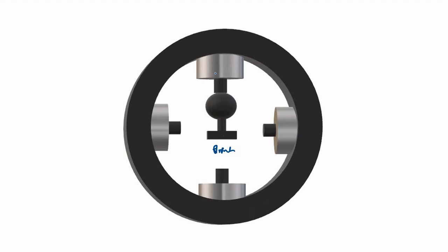Whenever the object rotates, it strikes the wipers placed at different positions, let's say the angular positions 0, 90 degree, 180 degree, 270 degree, and then 360 degree here, like this, 0 degree or 360 degree. Whenever it strikes a particular wiper, that particular sensor is triggered and gives the instantaneous position of the object and the total angular displacement.